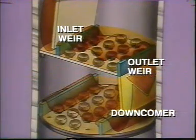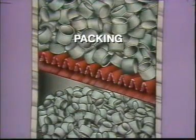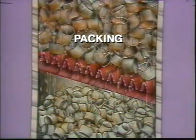Downcomers provide a passageway for liquid to flow down the tower. The downcomers can be designed to provide single or multiple flow patterns through the tower. Some distillation columns use layers of packing instead of trays to promote vapor-liquid contact. The packing material breaks up the liquid so there is a large surface area for contact with the rising vapors.